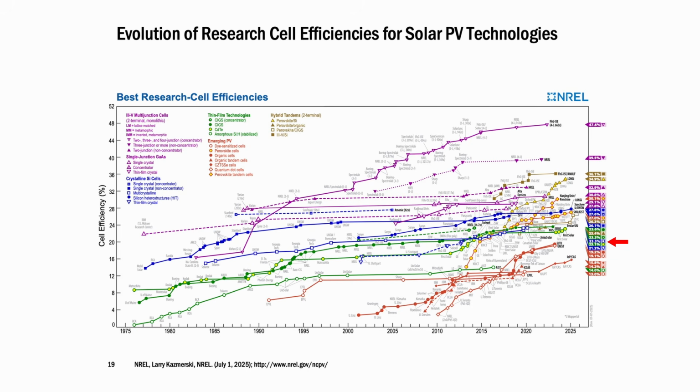You can get increased efficiencies, but typically the additional costs and the maintenance of all those moving parts with the mirrors, and the fact that you can't take advantage of diffuse radiation with the reflectors, outweigh the benefits of the efficiency increase. So we don't see a lot of concentrating photovoltaics being built today. I think there's maybe one at the radio station on the Dumbarton as you're crossing that bridge, if you want to keep an eye out for it the next time you're there.